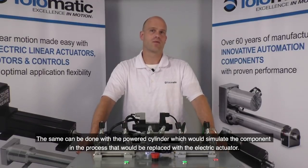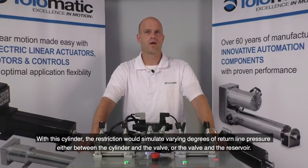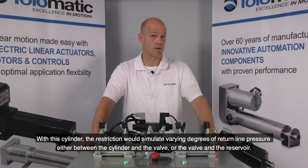The same can be done with the powered cylinder, which would simulate the component in the process that would be replaced with the electric actuator. With this cylinder, the restriction would simulate varying degrees of return line pressure either between the cylinder and the valve or the valve and the reservoir.